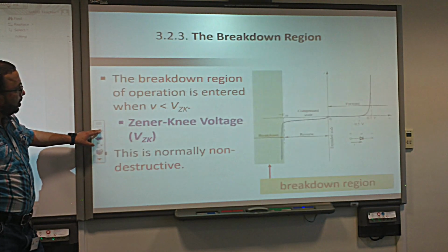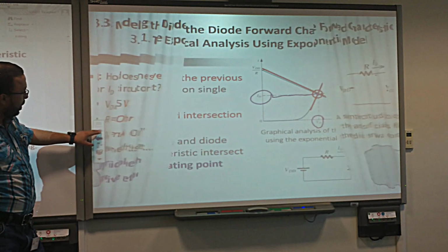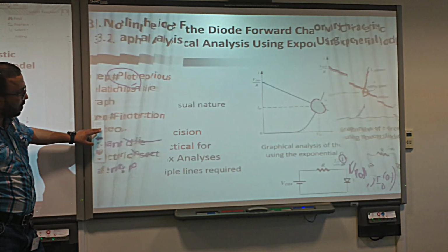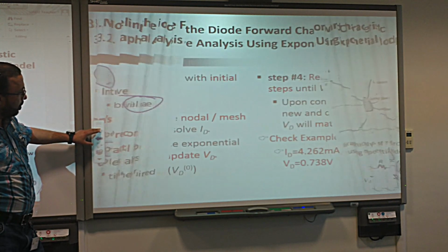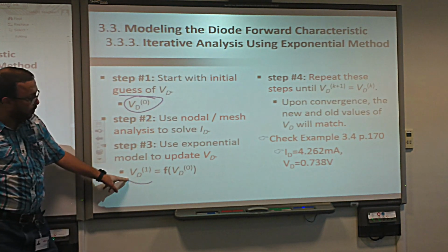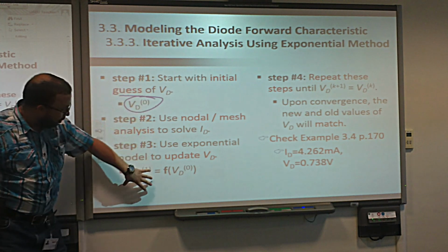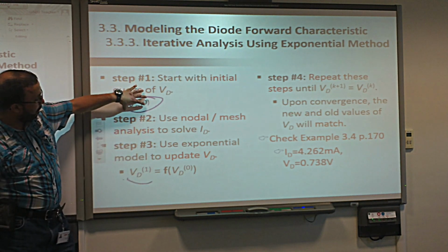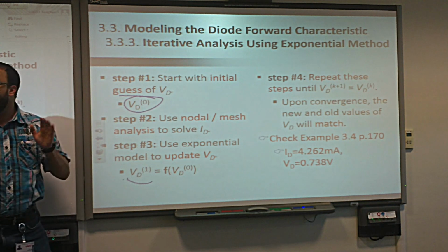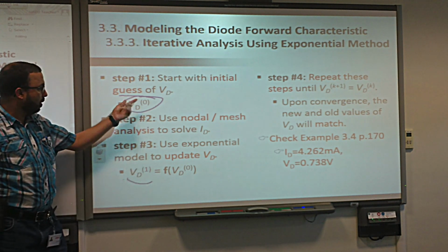So, okay, we'll go forward a little bit. Then after we do that, what will happen? Very simple. I found now the new voltage. I will check this voltage with the previous voltage. If this voltage is the same as the previous voltage, I stop. I say, I found the solution, it did not change. Now, if this voltage is different, I repeat.